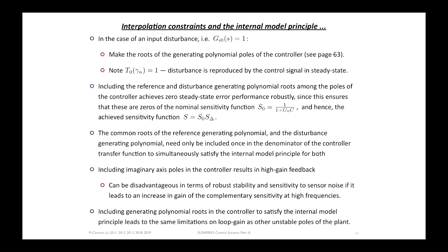And now we're putting open loop unstable poles in to get steady state performance. And in order for the closed loop to give you reasonable transients, we need to make sure it's fast enough. And to get it fast enough, you might need to pump up the gain of the controller to push the crossover frequency to the right,